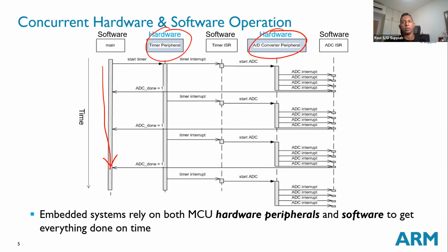Even though you have learned RTOS and know it's very useful, in many applications maybe you don't even need an RTOS. The microcontroller with its hardware and interrupts may already be sufficient to solve the requirements of the system. So we don't always overkill. If we can do without the RTOS, we just go ahead and do without it. But if we really need it, and it really helps us, then we go ahead and integrate it inside.